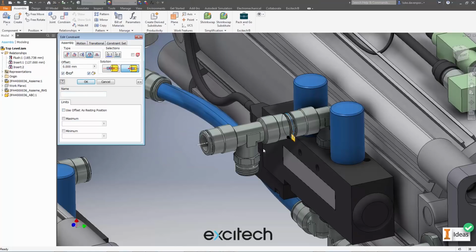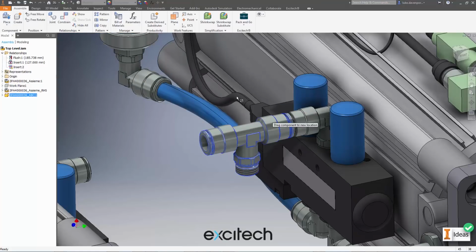However, the position of the twist is not negotiable with this. It will lock it in one orientation and one orientation only. So if I say OK, I don't have the option to flip it 90 degrees or anything like that. Okay, and if I do lock the constraint, I get a handy different icon here for the locked insert. Here's a locked one, here's an unlocked one. It's just something to be careful of here though.